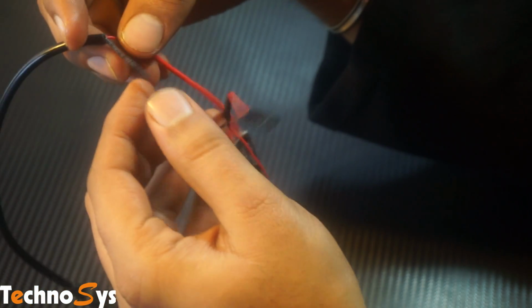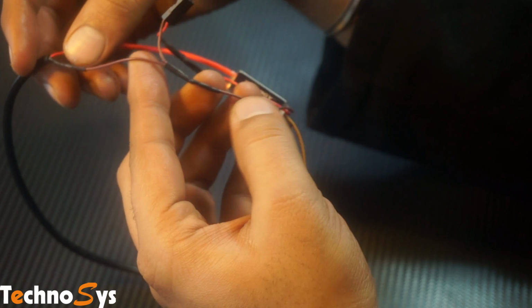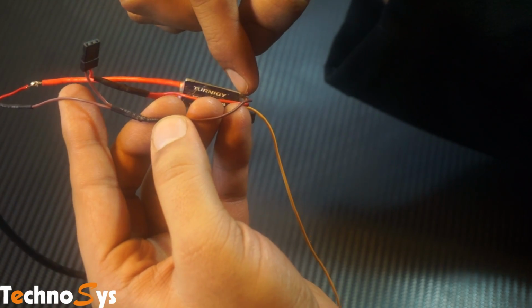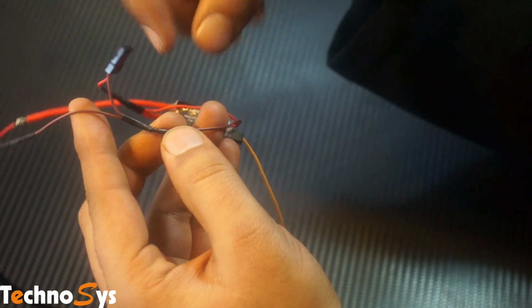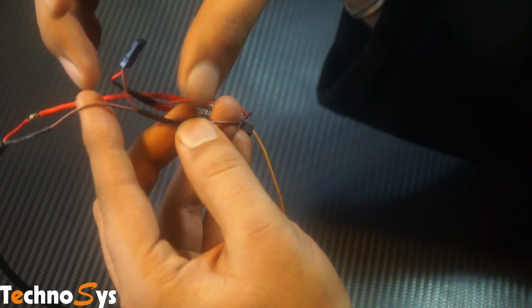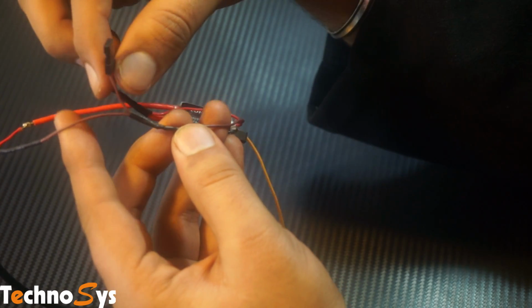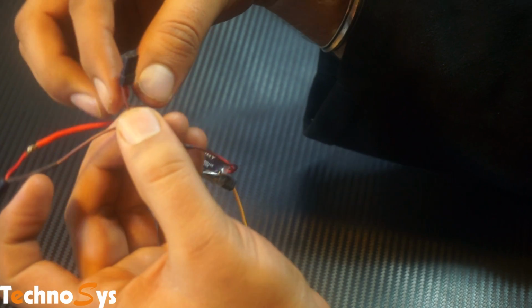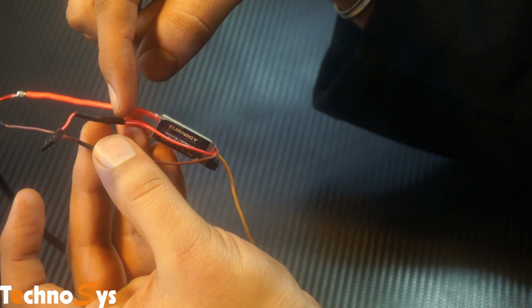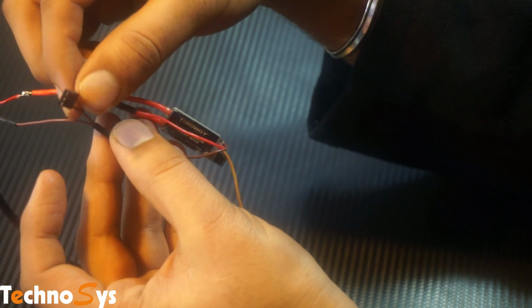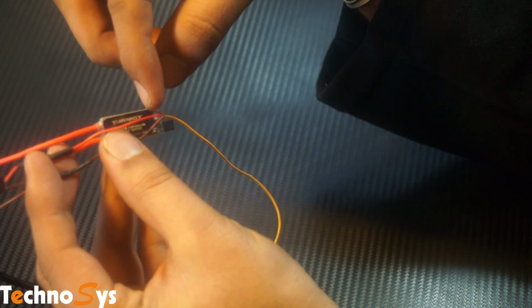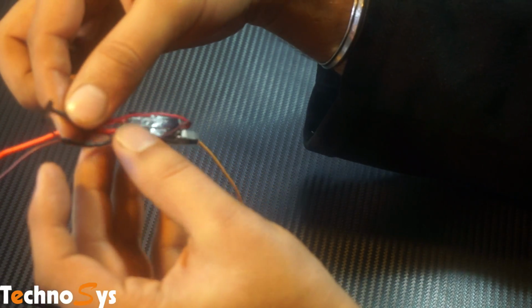We'll follow the black cable now. This is basically the negative, so it is going to be connected to the negative of the receiver switch, and of course to complete the whole circuit, you will also have another negative over here and connect it to this connector, and also take another positive from the receiver switch and connect it to this connector. At the same time, there is another positive coming from behind, also need to be connected here.